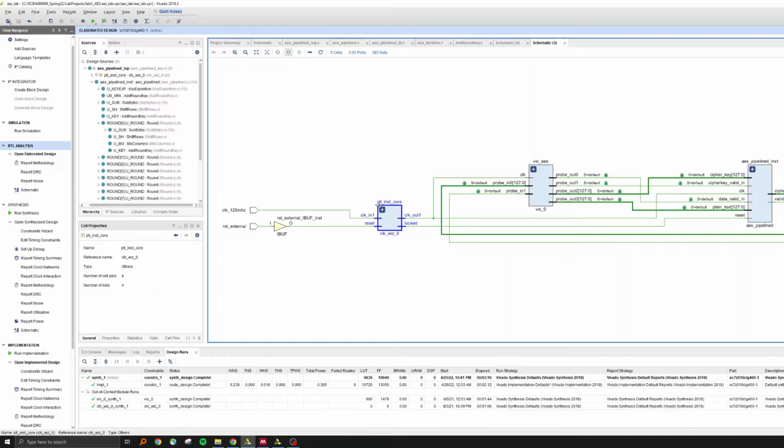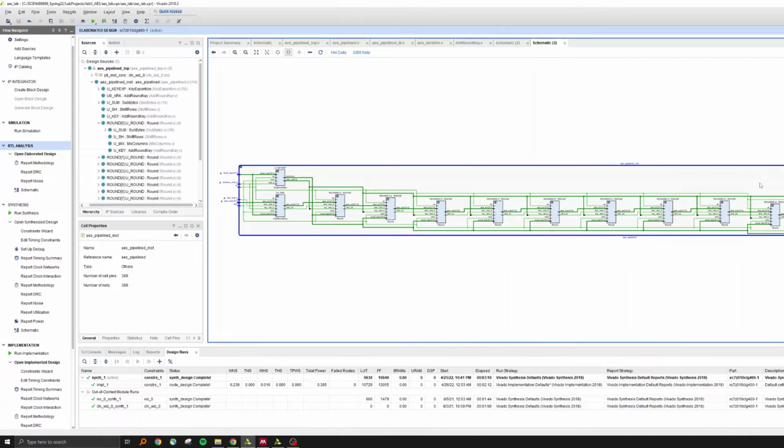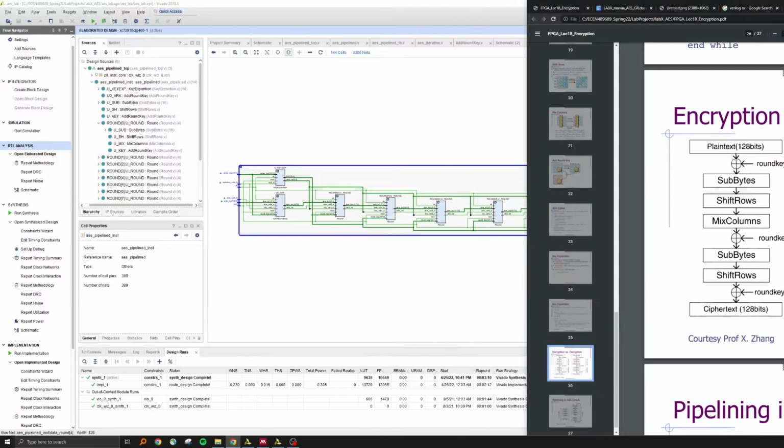All right. We have this PLL generating a stable clock for the whole design. We have this VIO. VIO is like an oscilloscope within Vivado, right? It has a lot of probes connecting with the design so that you can see the real-time values of them within Vivado. And also we have the main part in this design. If you double click into this, you can see the details. The details are basically summarized in this diagram.